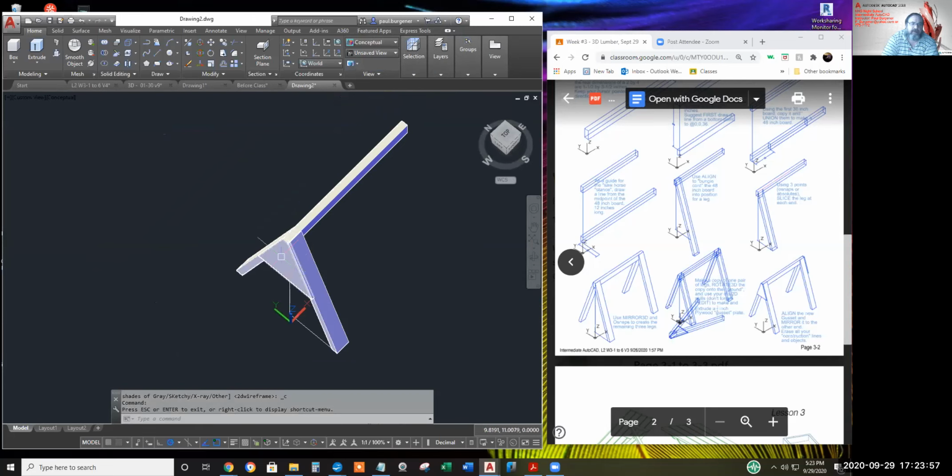Now just a matter of mirroring the two legs and the plywood about a plane at the midpoint of the top 2x4. You know, I think this would be a case where the two-dimensional mirror command would be a click quicker. Drop down, select two-dimensional mirror command we learned. Select all three objects, shift and deselect that chalk line, which I should have erased already.